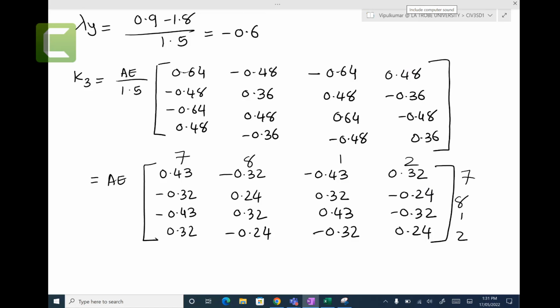I will give you one trick that you don't need to write all of them. Right? You don't need to write all of them, meaning that it will be an 8 by 8 matrix. So it is a lot of numbers, but I will give you a trick. When you do the calculation for displacement and for reaction forces, there are three calculations: reaction force, internal forces, and displacement. I will tell you in the assembly of the matrix, you don't need to write all of them.